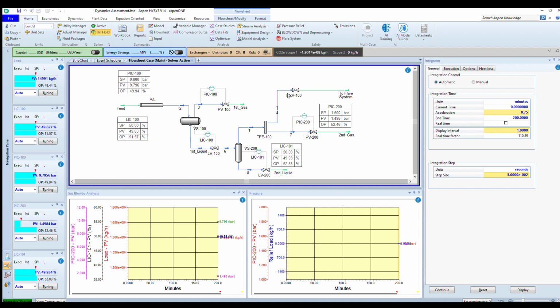This is the element of reality and the accurate prediction, accurate calculation of a specific parameter. This parameter is so crucial down the road to reassess the associated process piping connected to the PRV, upstream and downstream, all the way to the tailpipe and the flare knockout drum.